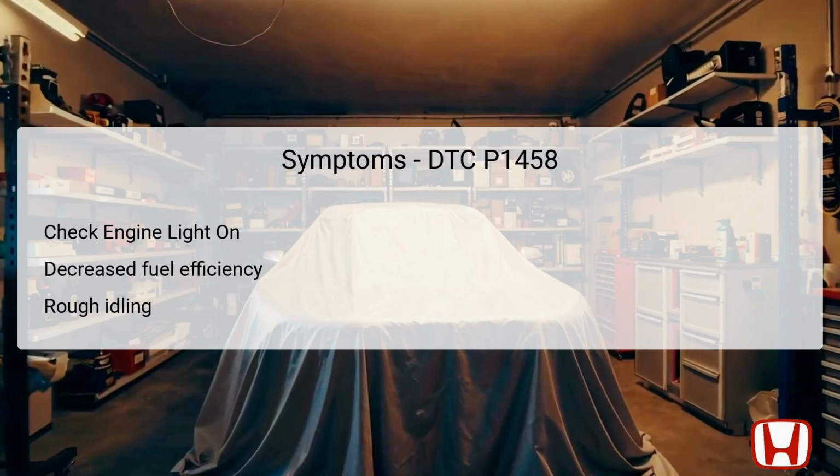Additionally, rough idling could occur if the engine is receiving inaccurate airflow or pressure information, leading to unstable operation. These symptoms provide essential clues that aid technicians in quickly identifying the underlying problem affecting the fuel system. Timely intervention can prevent further complications and more significant repairs down the line.